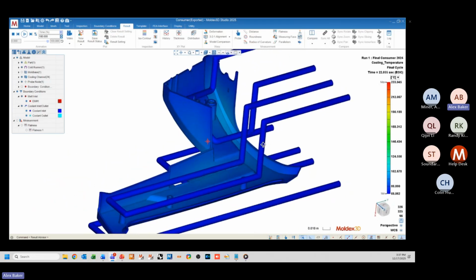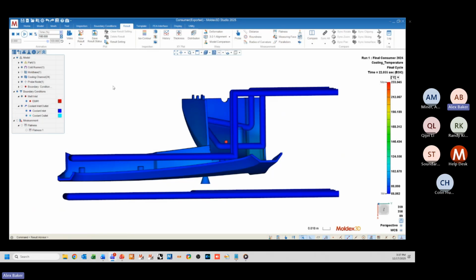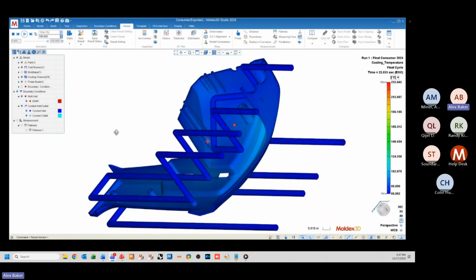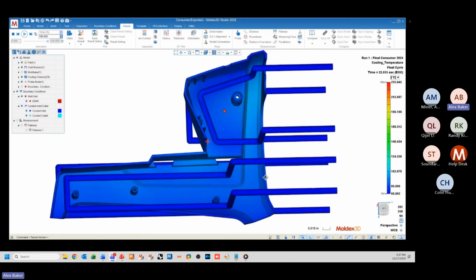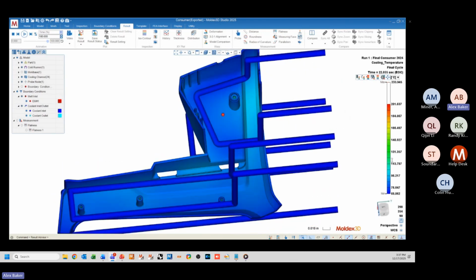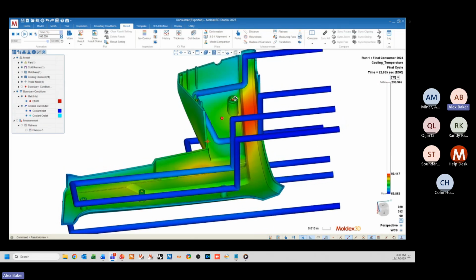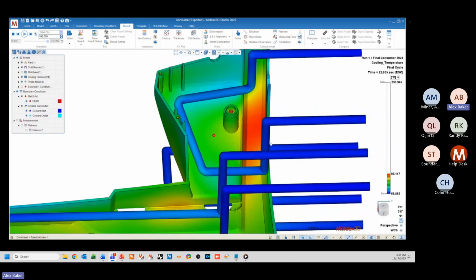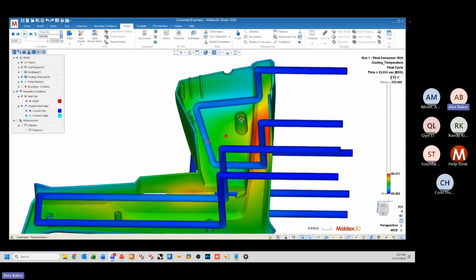Unlike the model setup that we did for the project earlier on, where we used kind of straight channels across our mold, in this case, I actually got a little bit more conformal with the cooling channels. The cooling channels go quite a bit closer to the surface of the part. What we can actually see, if I recreate that temperature distribution that we saw earlier, is that that heat accumulation happens between the inlet and outlet of this cooling channel going on the bottom side, which is interesting.